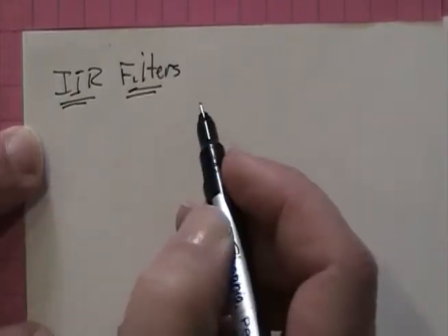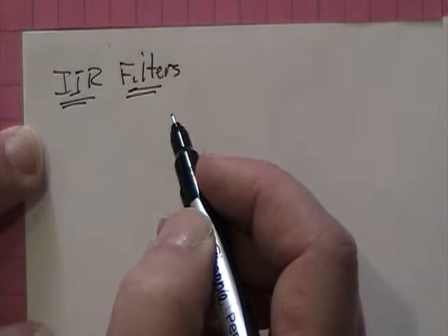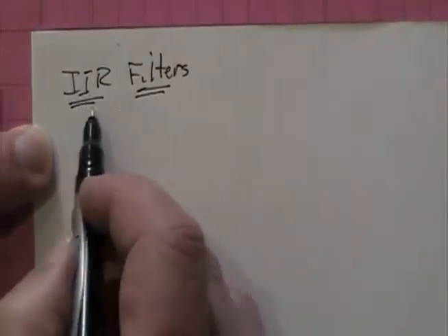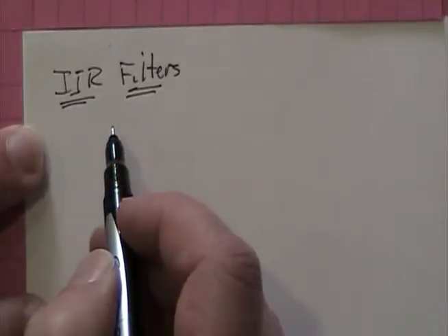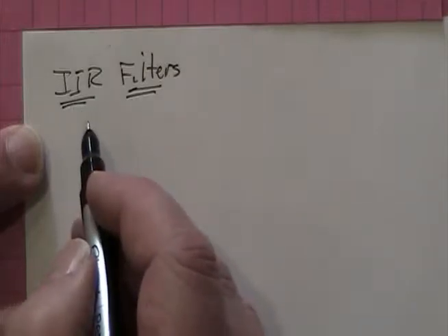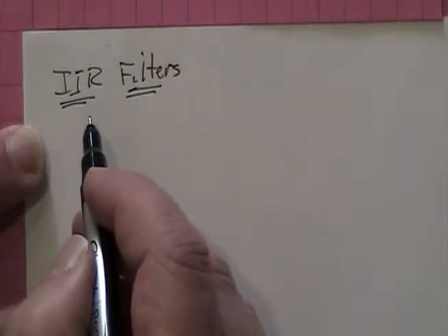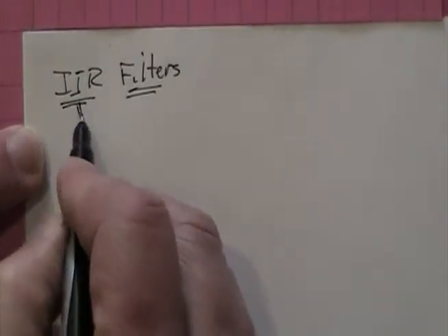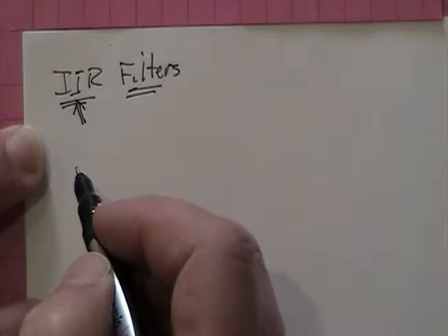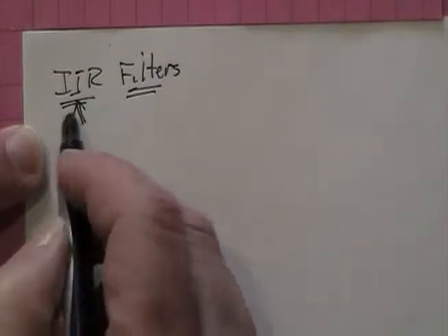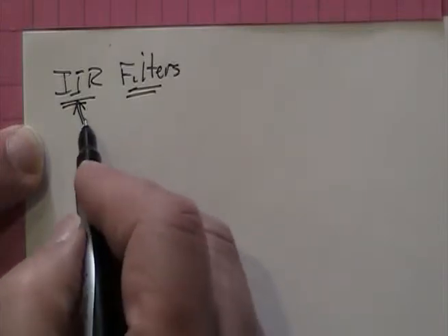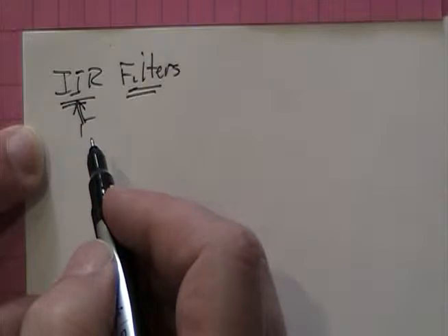When we talk about numerical stability on IIR filters, there's a ton of work, and there's actually a pretty good segment in your book about how to model rounding errors. Particularly if you're dealing with integer math, it becomes a huge issue to make sure that filters are numerically stable. Numerical stability problems end up being more important for the IIR filters than the FIR filter cases. The FIR filter cases can never go unstable, but everything we do here really applies to either the IIR or the FIR case. More commonly, we're going to deal with it for the IIR case.